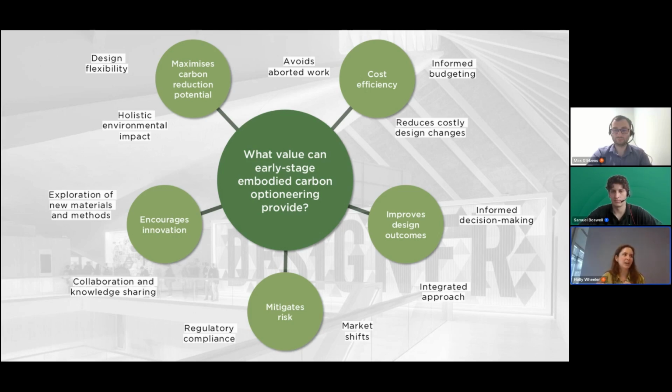There's also the ability to collaborate with the design team. So we saw that with the different structural optioneering. Although we had the whole life carbon analysis underpinning the different structural optioneering options, and we could see which one had the lowest carbon impact and which one had the highest, you also have to balance that with all of the different other design considerations. So for a lab space, it just wasn't feasible to have a timber construction on the typical floors because of the response factors. And that was okay because we understood that collaboration with the design team and ultimately went forward with the best approach.